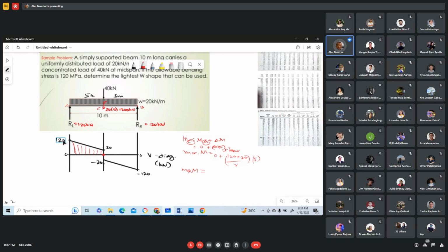What is now our maximum moment? Do you have your calculator with you? 120 plus 20 is 140, over 2 is 70. 70 times 5 is 350, right? Is it correct? Yes, sir. Okay, thank you. 350 kN-m. So we know now the maximum moment.